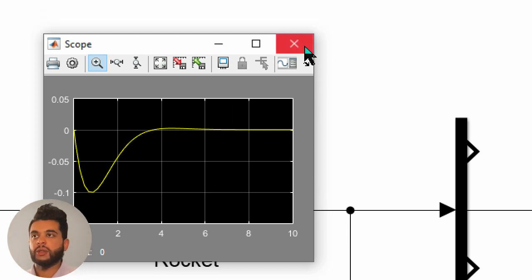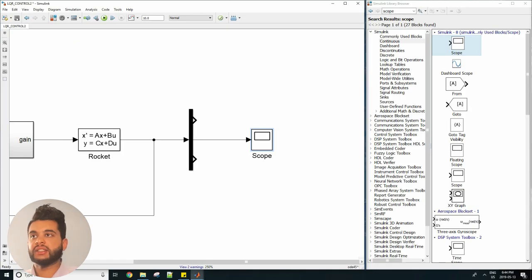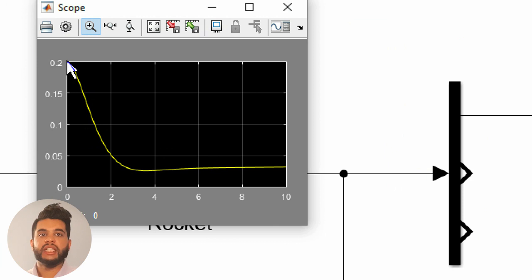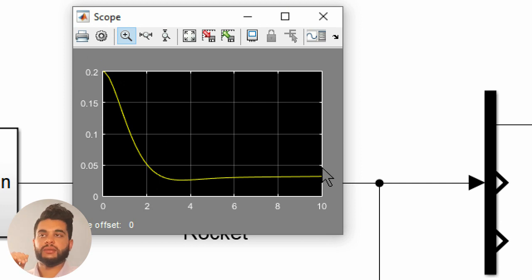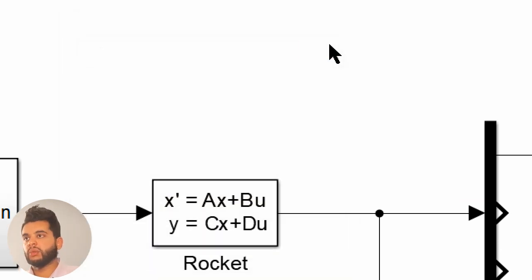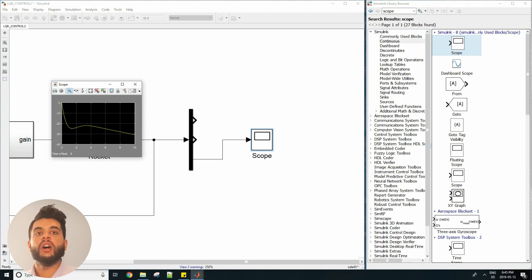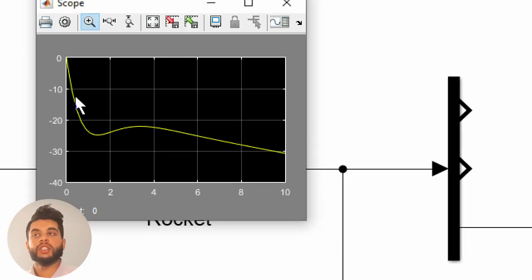Let's drag in the scope and take a look at the angle itself. The angle first goes down a bit because we have a TVC input, and then it stabilizes, because when you change the gimbal angle the rocket will turn and then just stop moving. Also taking a look at the drift, because we do have wind and uncertainty in the system, you will have drift for sure initially, because you also have Z motion, since the pitch angle is non-zero.